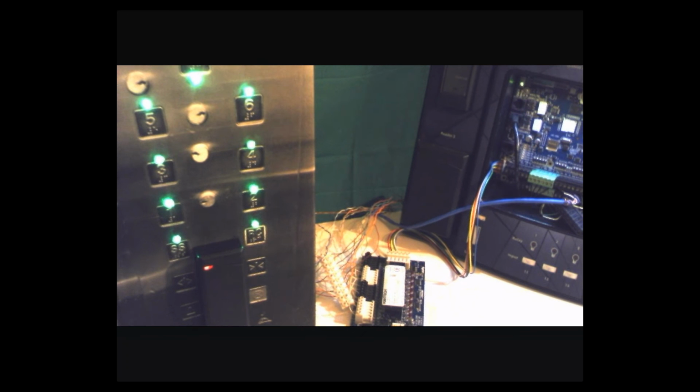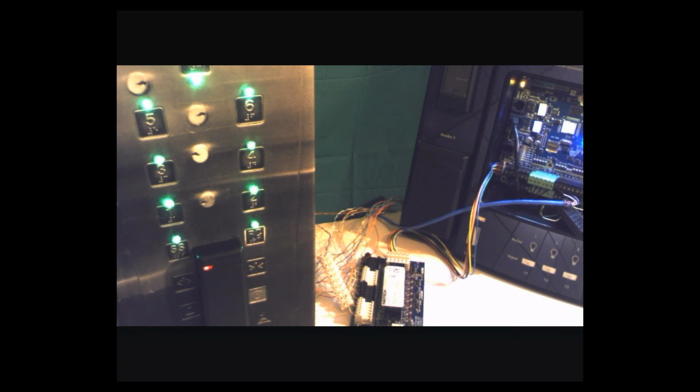As for the elevator equipment itself, let's take a look. Right now, we have all the floors enabled. If somebody gets in that cab right now, they can go anywhere because the elevator control is not programmed yet. When it's not programmed or when it's down, it's the same situation. For example, if the customer shuts down the elevator control, the elevator will be free access. You can go to any floor. So once we activate it, start the programming and enable the relay module, all those floors will be inaccessible, no access until somebody swipes with an access granted, allowing them to go to some specific floor.